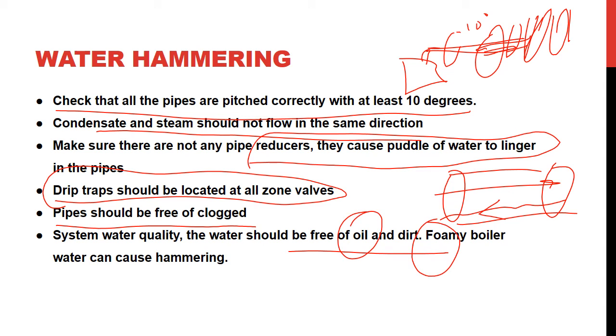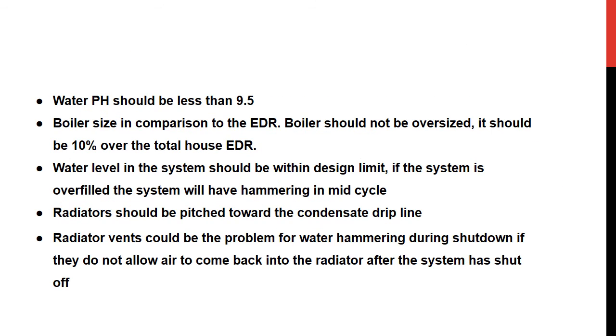If you have foam, then you have blockage, and that blockage can cause you to have water hammering. Again, water hammering is one of the most common problems with steam. It's very frustrating, but again, eventually it happens.